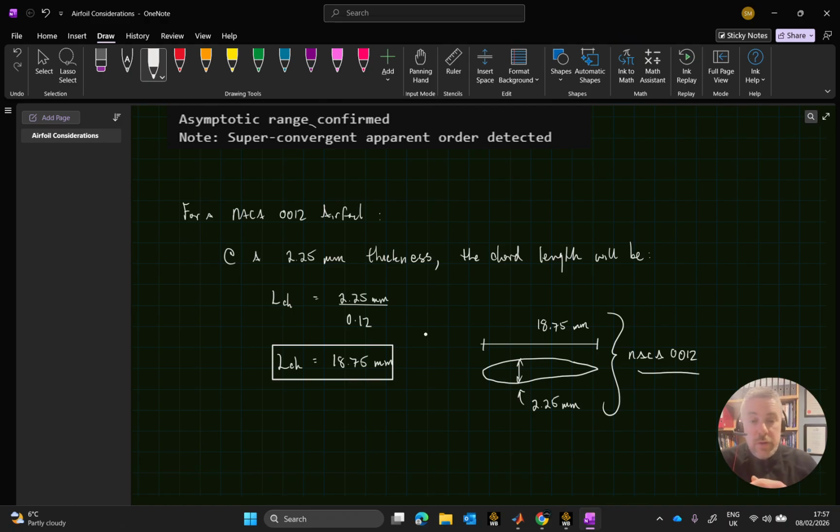And of course other airfoils might share similar dimensional characteristics with respect to chord length and dimension. So running with the NACA 0012, again, I'm just using that because it's an easy one to generate using the 4-digit generator on Airfoil Tools. We have plenty of data on it, but there are other airfoils whose thickness is 12% of the chord length. So you're never going to be restricted to using the NACA 0012, but it'll give us a good idea.